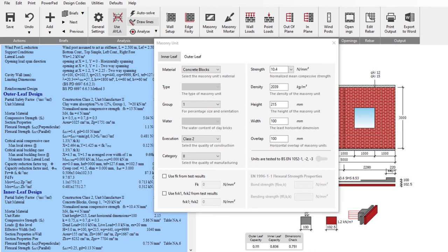Do you need to change the densities? The densities seem to be 239. Good question. The density of block walls changes and varies considerably, with strength and with composition. So yes, you can go in and change these values to be what you want. The density is only used to improve the flexural strength, most significantly the flexural strength of the wall in the x-axis. So yes, watch your densities is the simple answer there.